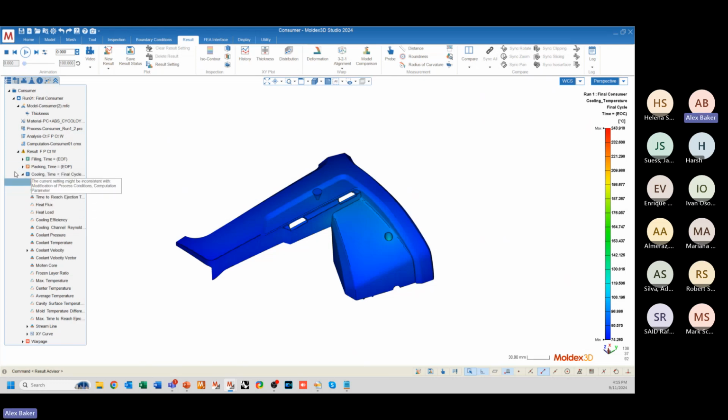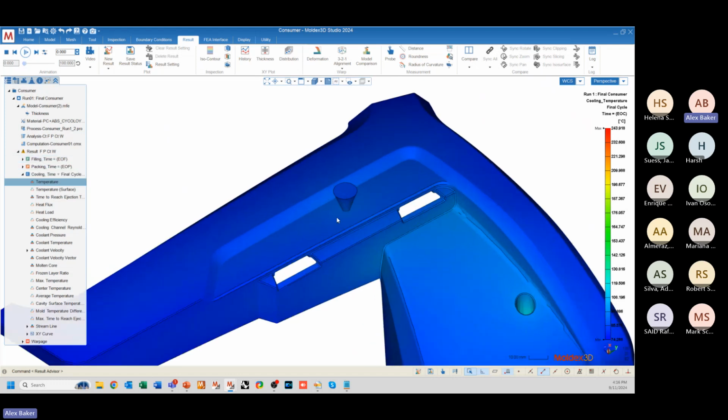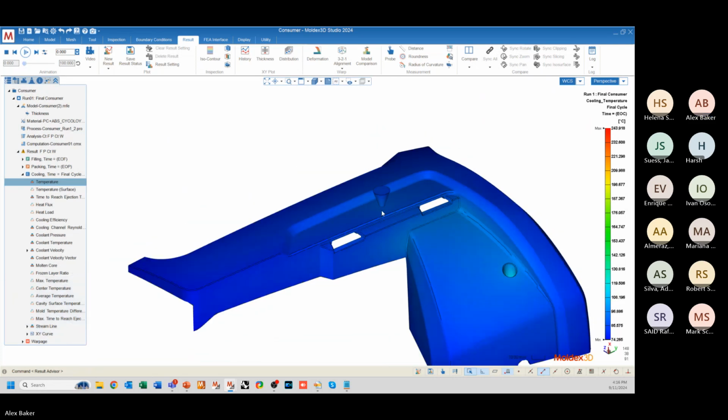All right, so all of that leads me into the warpage analysis. So in the filling stage, we evaluated the temperature distribution, which is implied by how fast the material was feeding through my part geometry. We evaluated the pressure distribution in the packing stage, which allowed us to see how the packing effect, or the compression of material into my geometry, is combating the natural shrinkage effect.